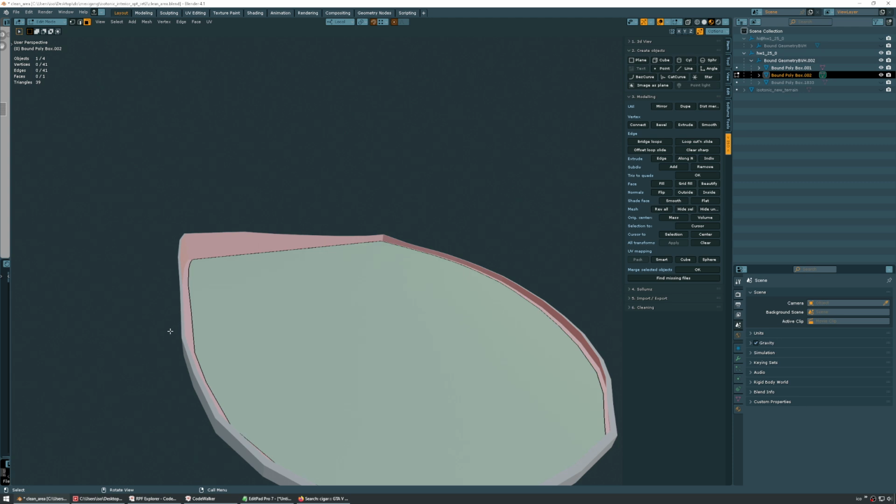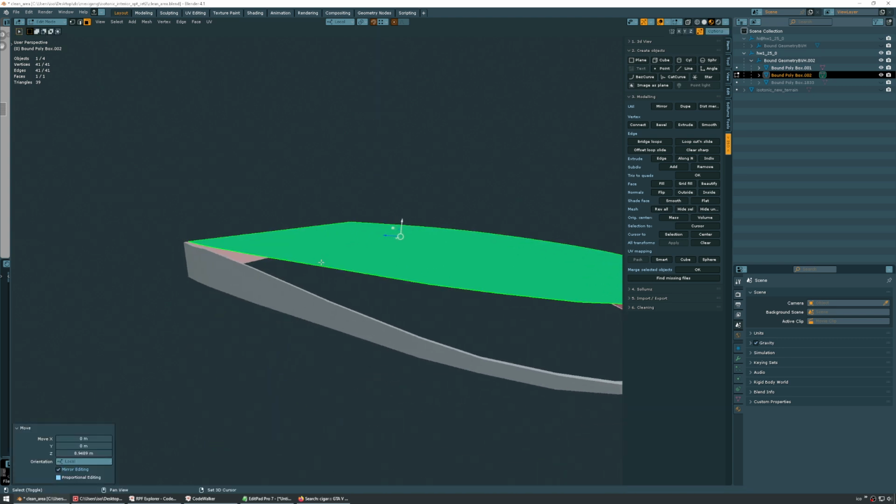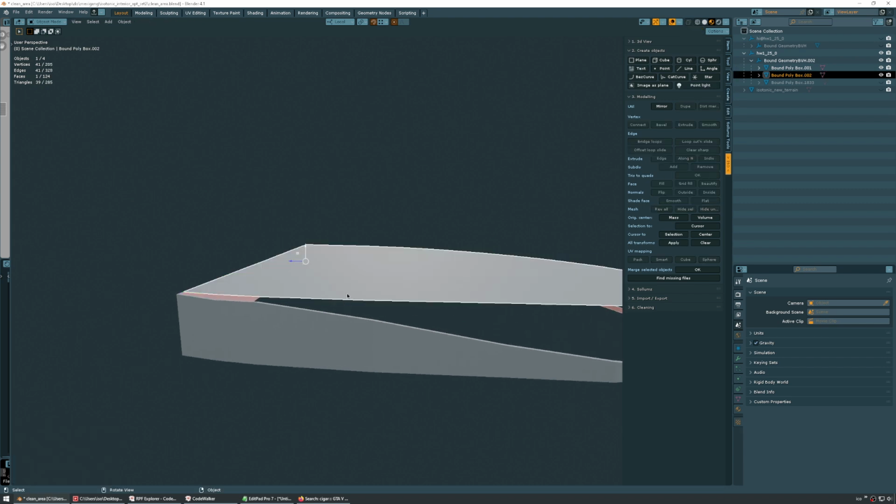And double flip the normals from facing downward and it will face upward. And then you can just snap it to what it needs to be. And if you need to, you will need to readjust the vertices for this mesh